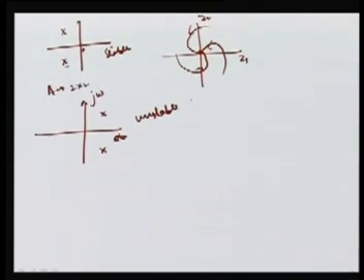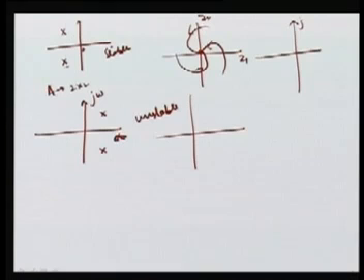No doubt, in this case it will also be oscillating. If your poles are lying here on this side, where this is j omega and this is alpha, your system response will be decaying. With free response, if you perturb it and there is no force, the system will come to zero.